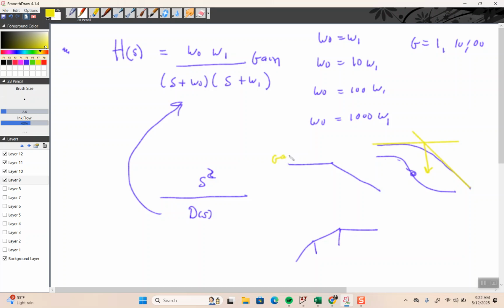The gain, the cutoff frequency, and that slope is really all you need to know. And the phase, right? Because the phase will tell you, like, is it inverting or non-inverting?